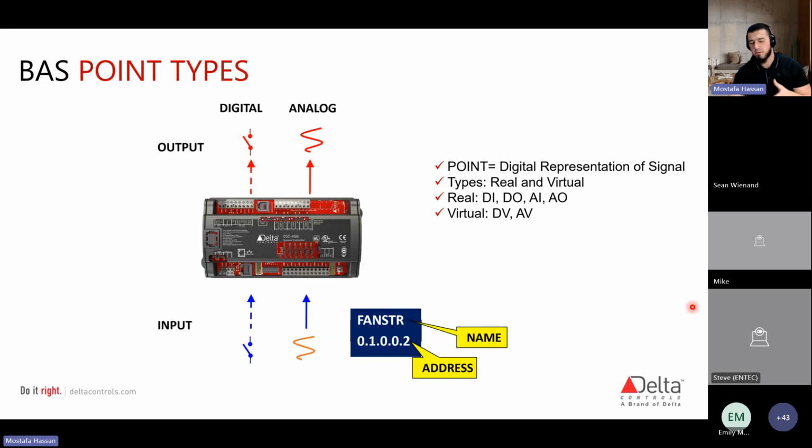And these are some things that Emily will take you through in BAS 103, right? As she dives through systems and boilers, chillers, cooling towers, different types of controllers can manage certain types of systems depending on the size. And that's something I also mentioned on the architectural level, right? You have supervisory and application specific. So the larger the system, the more demand for a larger controller. Every device that's read or monitored or controlled by a controller is turned into a real point. For example, temperature sensors, current sensors, meter pulse inputs, and valves.